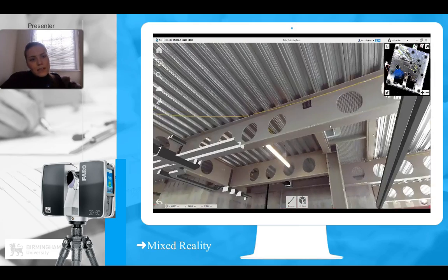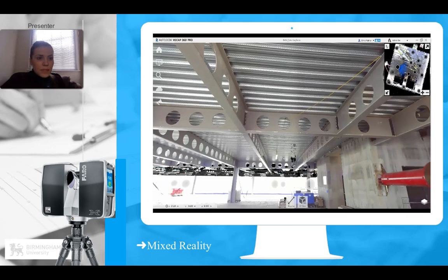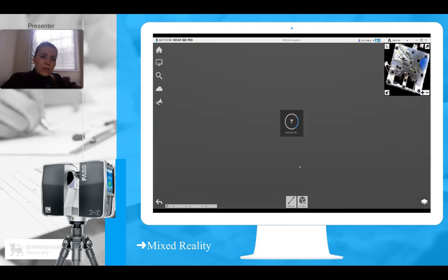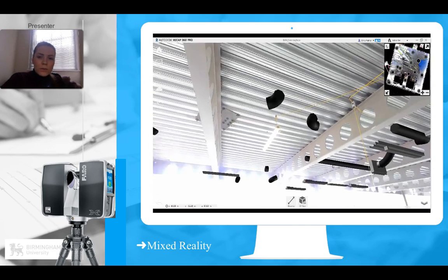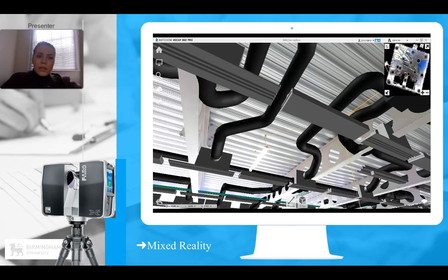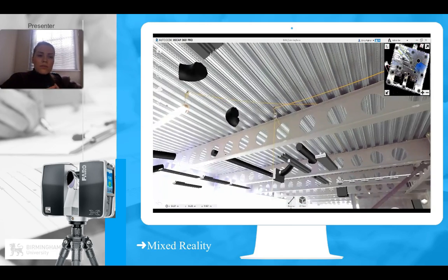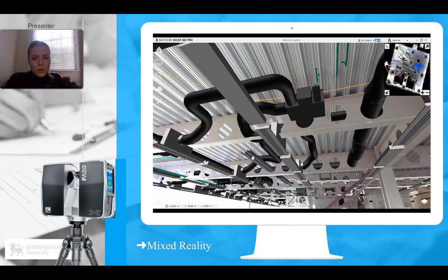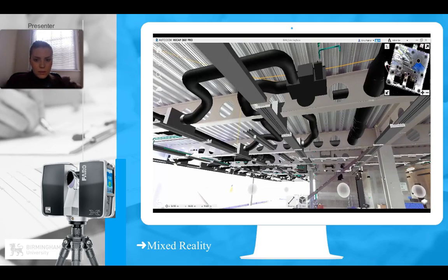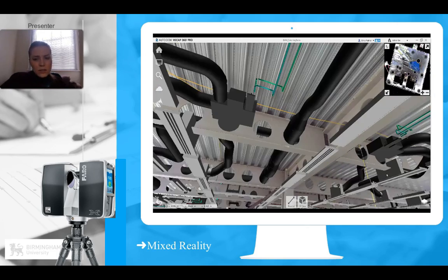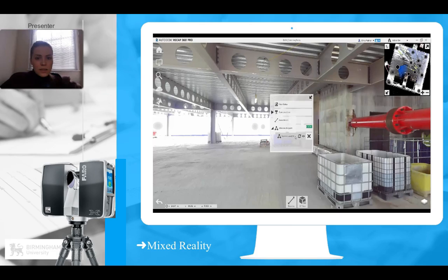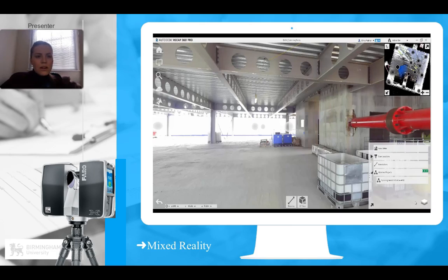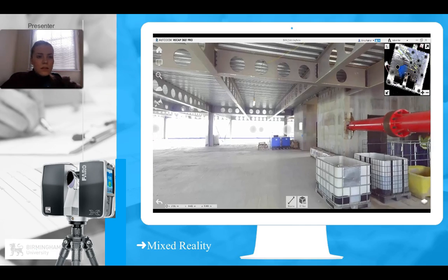If we are going to be handing over as-built BIM models, then to better make use of them with the physical world, we can start to integrate them with mixed reality solutions, where the BIM models or the components can be overlaid in the field of vision of the BIM tablet itself, when it's looking and scanning over the existing physical elements within the building. It's a similar approach to the barcode system, whereby you scan and you retrieve the data, but a mixed reality solution allows a direct overlay of the BIM data with the physical world.